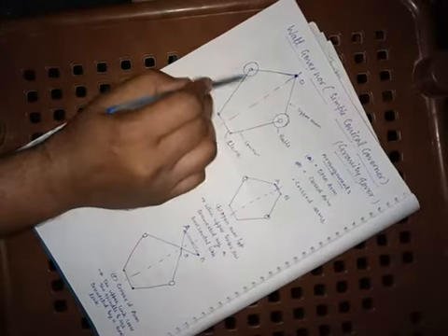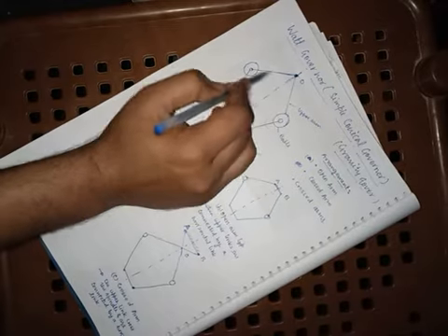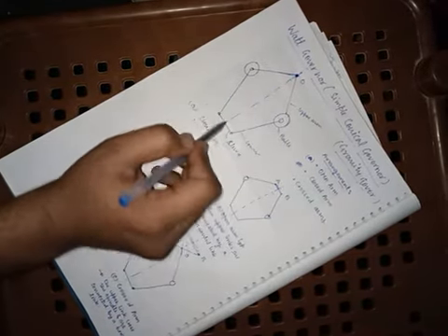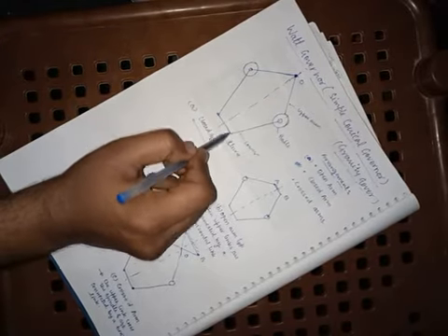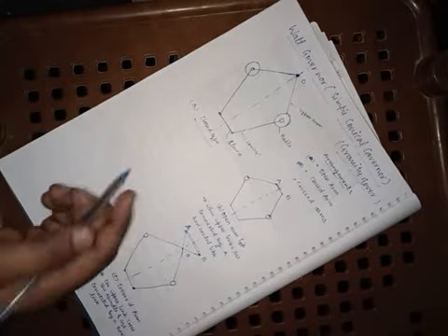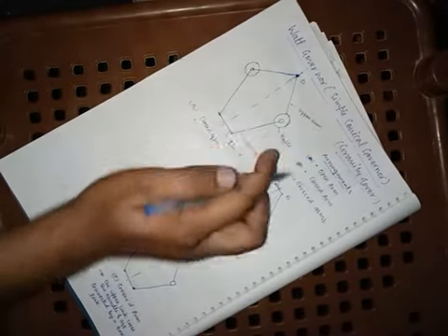So now you can define a simple governor. A simple governor is a simple pendulum type or simple centrifugal type of governor that has two ball masses whose upper arms are connected at the spindle and the lower arms are connected with the sleeve. So you just explain whatever I have explained in the last figure. As soon as the speed increases, various forces act.